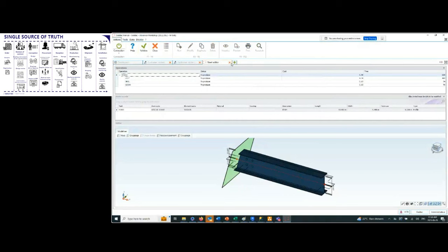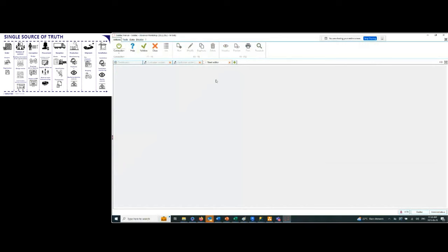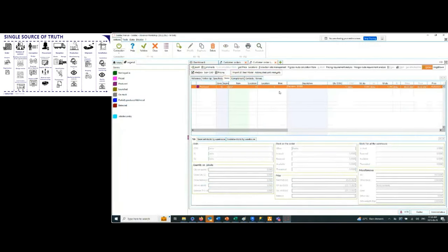And again, this would only be for small projects, or if you had a quick revision to manage on a project, for example, hole spacings on a plate, that could be done with the CAD editor as well. But whenever there's an actual revision on a project, it's always best to go into the actual models, the CAD model, make your necessary modifications, because one modification can impact many different objects in the project, right? Numbering and things of this type as well, which can cause issues with coordination down the line.